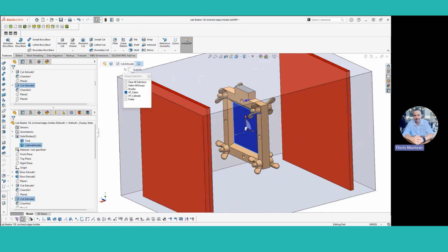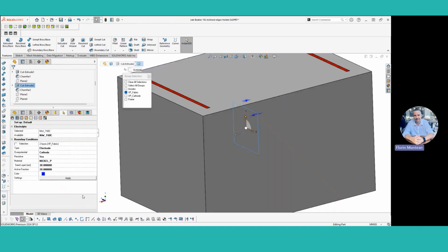So it's kind of a 2D surface. But in reality, this fabric has a few layers on top of each other. So in order to mimic the behavior of such a layout, we use this option available in Elsyca Plating Master, which is called active fraction.